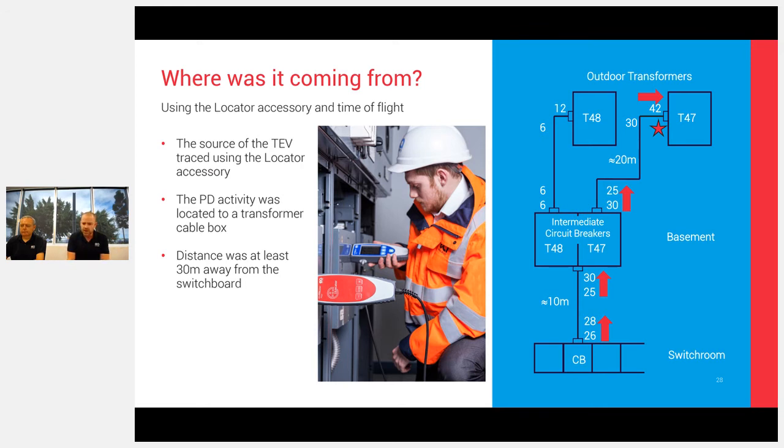Sometimes it's not where the highest signals are. There have been many case studies where we've found it's not necessarily where the highest are. What we did in this one is we found that at that circuit breaker, the switchboard down the bottom of the diagram, is where the UltraTEV monitor was monitoring for a week. When we came along with the UltraTEV Plus2 instrument, we measured 26 decibels on the board and